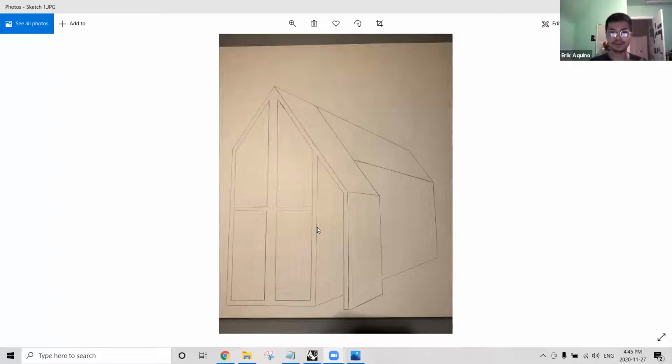So when you're starting to model, I suggest doing a few good sketches that are axonometric or plan, elevation view, and analyze what the main parts of your building are. So we've got this profile, which looks like we can extrude. And when I say extrude, we're giving our 2D profile or 2D surface a thickness.